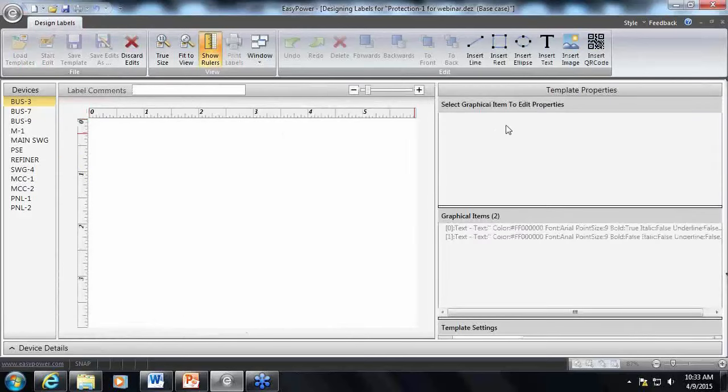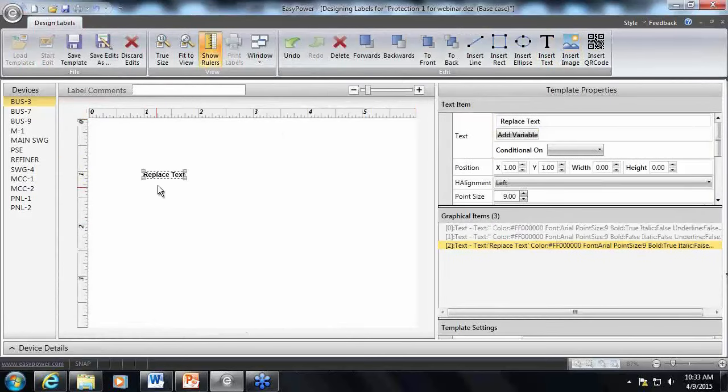Go to Start Edit, and I'm going to add in a text box. So I am adding in a new text box. It gets placed, and what I want to show here is one of the references in the NFPA 70E, a minimum arc rating of clothing. In your label, you may not want to show, for example, the incident energy that's calculated as 3.2.